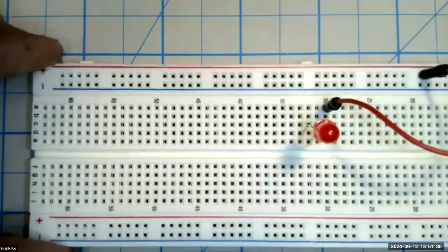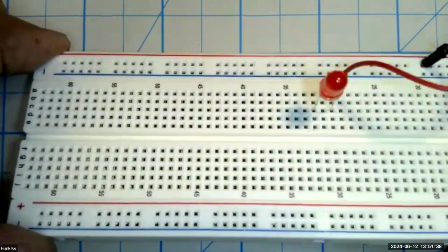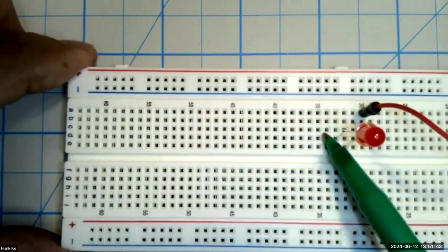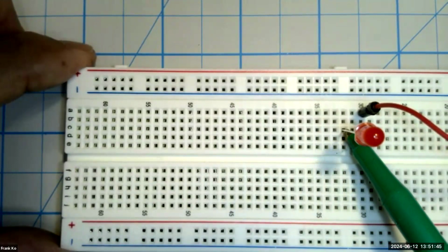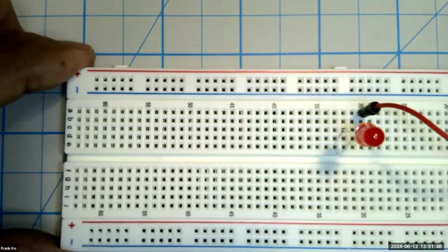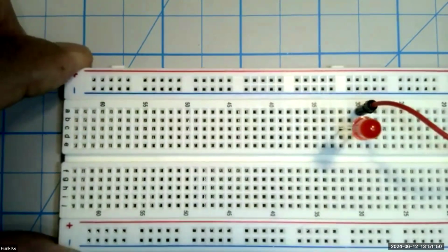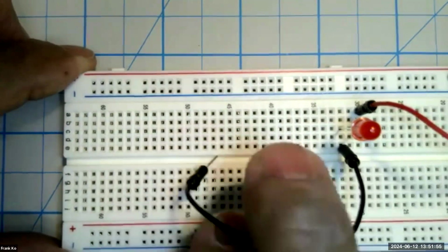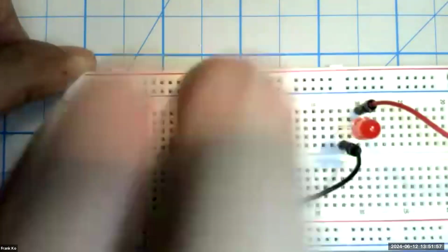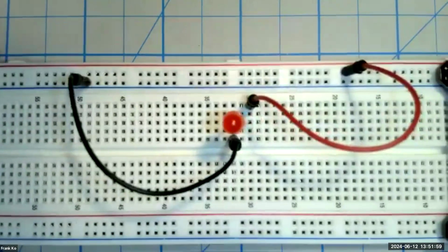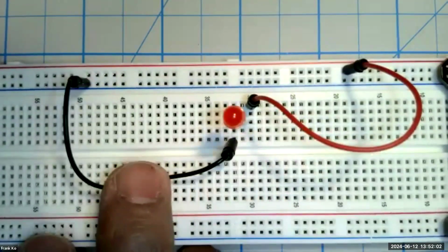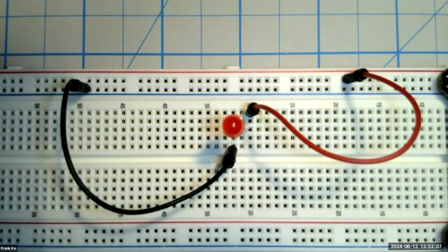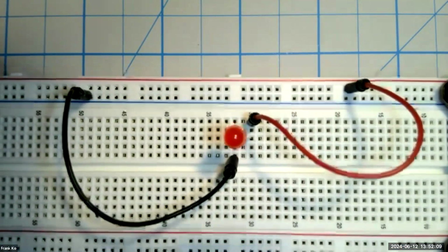Okay, then we're going to take the black wire, and the black wire's got to go to 32E. So here's row E over here, and 32 puts us right there to line up with pin 32C of the LED. And we'll go here, push down, and then the other end of the black wire anywhere on the blue rail, like so. Okay, so there's your circuit build, your very first circuit build, and we're now going to see if this guy is going to work properly for us.